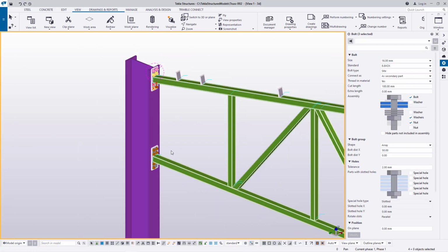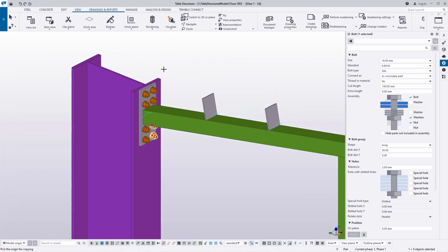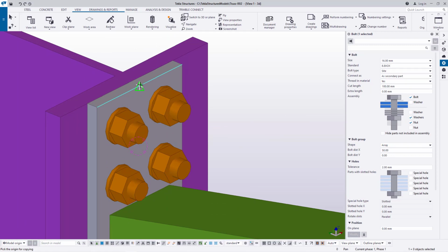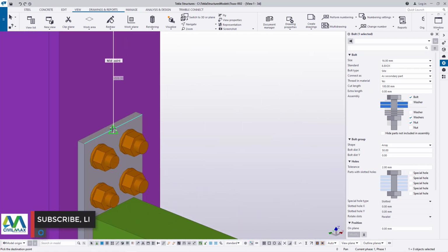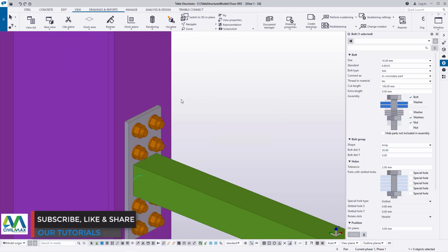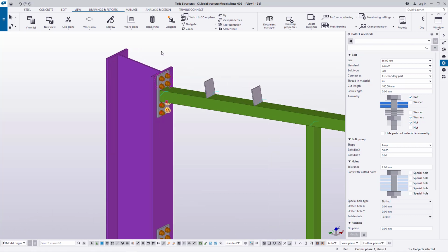So we've left some components, some bolts, so we'll just select on that, right click and come to this far end or this point. We'll snap on that spot and come back and copy them on the same spot. Right click and interrupt to terminate that command. So we'll do the same thing at the other end.